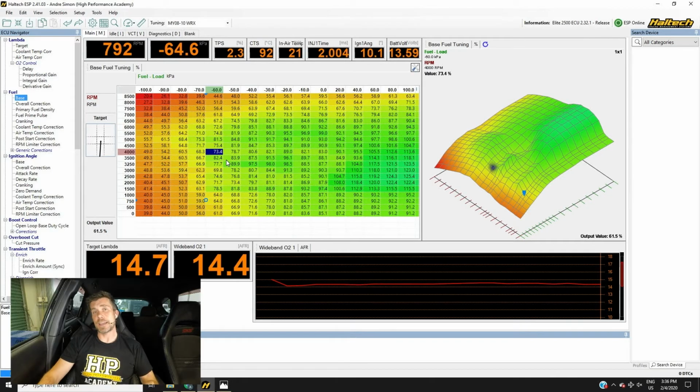I have had a couple of turbocharged race engines where, for no obvious reason, on tip-in at medium RPM, so let's say 4,000 to 5,000 RPM, where the turbocharger can produce boost very quickly, we'll find that on a sharp throttle input, the engine suffers momentarily from a couple of hits of detonation, and you can audibly hear that.